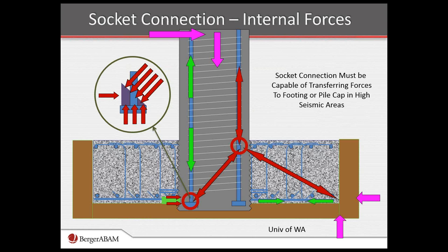Since this column is straight, this shows that system of connections where the column now has headed bars on it to affect force transfer between the column steel and the footing. It relies on confinement of the reinforcement in the footing around the column in a corrugated interface. This actually produces a very good force distribution within the footing, we think better even than bars that are typically turned out in cast-in-place construction.